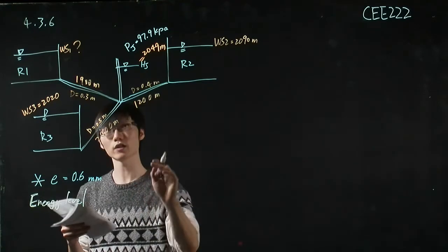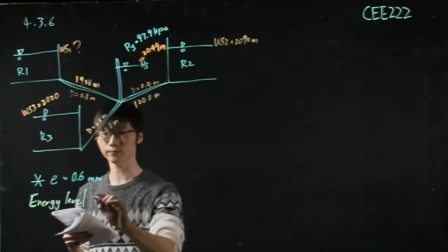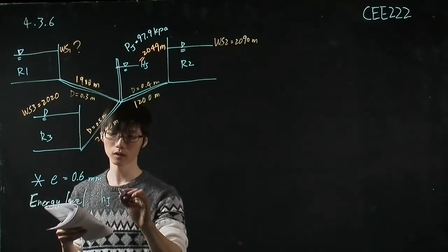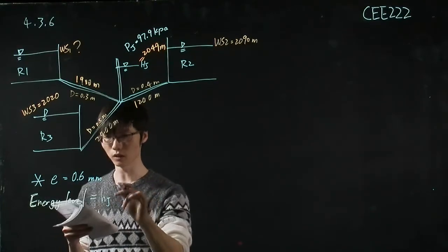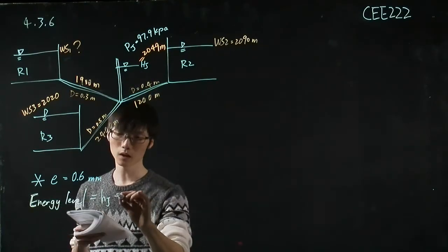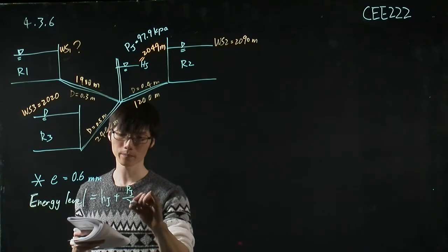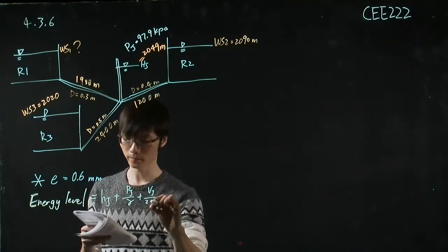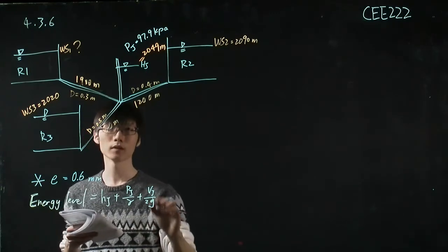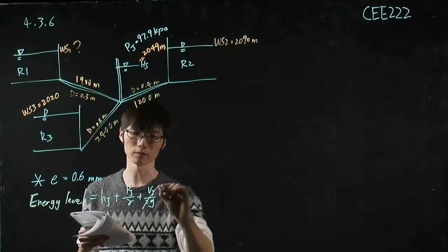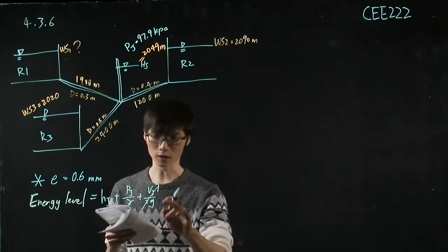Using the information that we have at this junction, this will equal the height of the junction, the water height in the junction, plus the pressure term, plus the velocity term. Because this is a stable system right now, we don't have the velocity term.